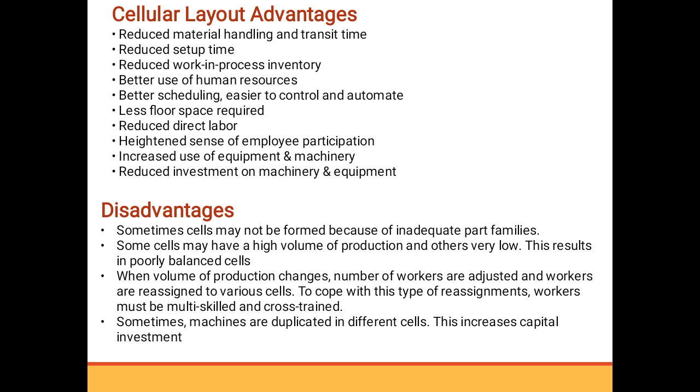Now there are different advantages of the cellular layout. Here the material handling is reduced, also the traveling time is reduced. Setup time is also reduced, and work in process inventory is reduced. The human resources utilization is better, and scheduling and controlling is easy.